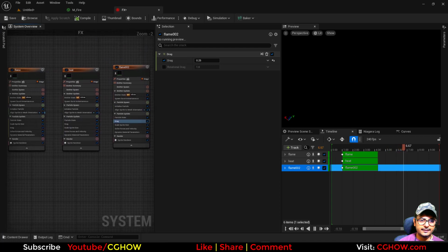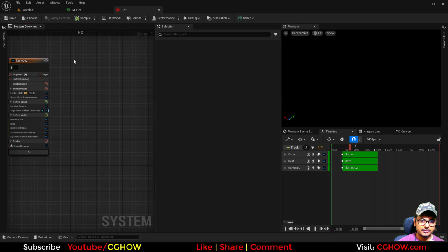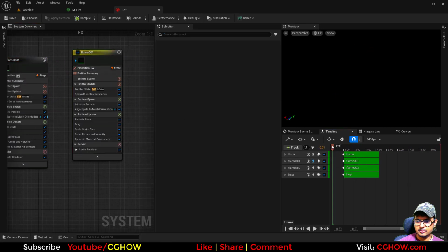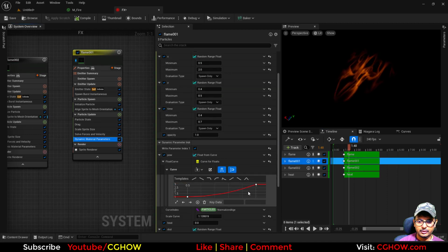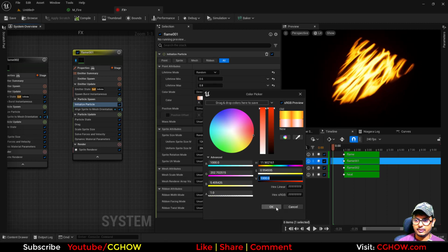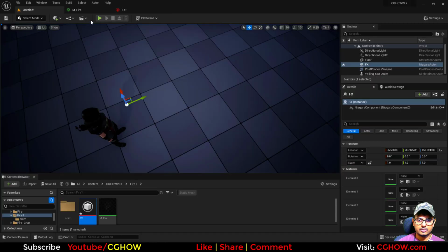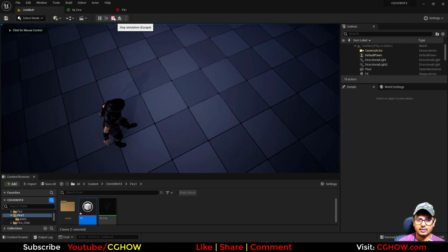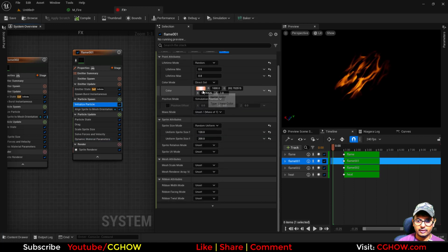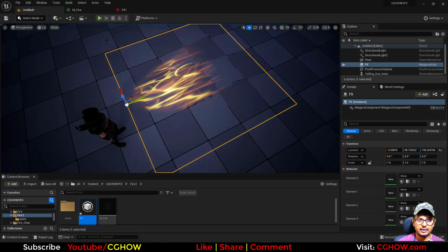And then at last, I'll copy these flames again, these ones. And what I'll do in the dynamic parameter, first I'll increase the glow, color brightness, maybe 1000. And then in here, this power, I will decrease this. So I will have just the lines. So if I play, not visible much, so I will increase it even more, maybe like this.